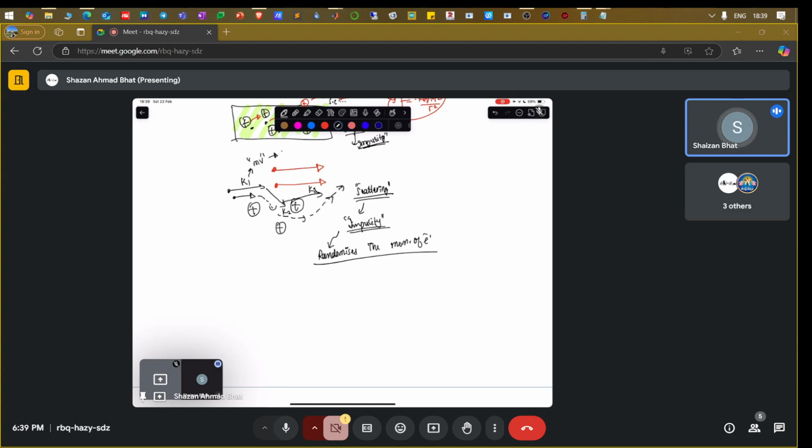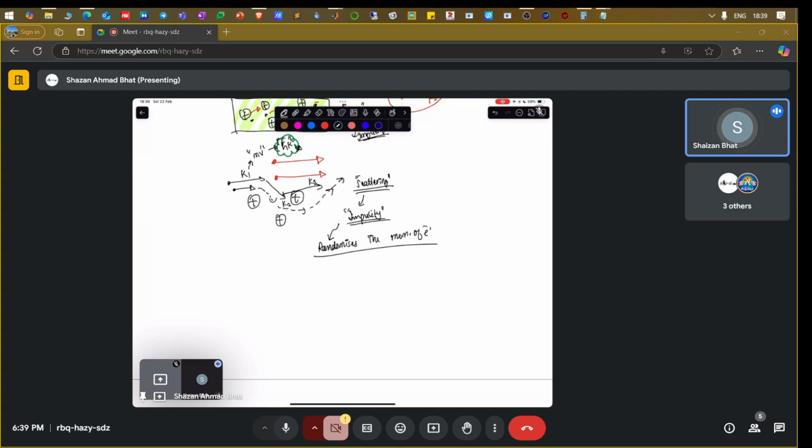But for the electron moving in a crystal, it's the product of h bar times k, where k is the wave vector. This is called the crystal momentum of the electron moving in a crystal. Let's not talk about the difference between the crystal momentum and the actual momentum, but it totally randomizes the momentum of the electrons.